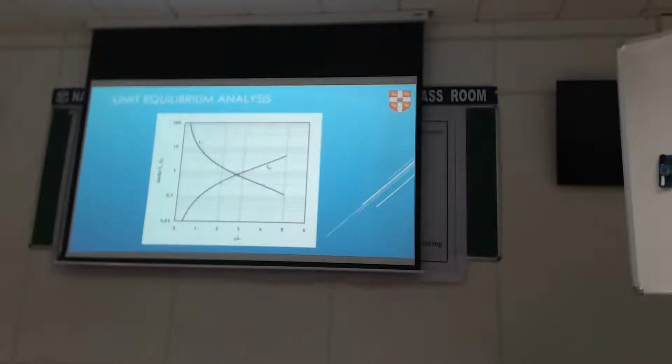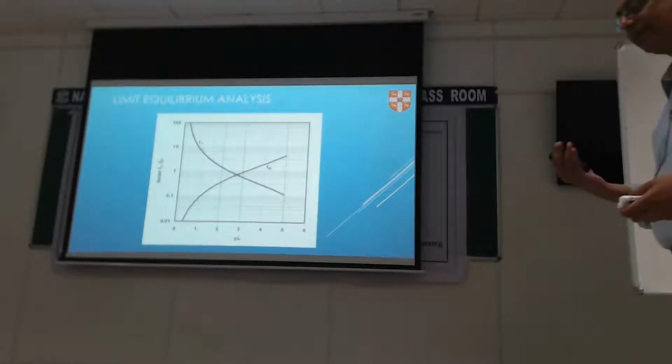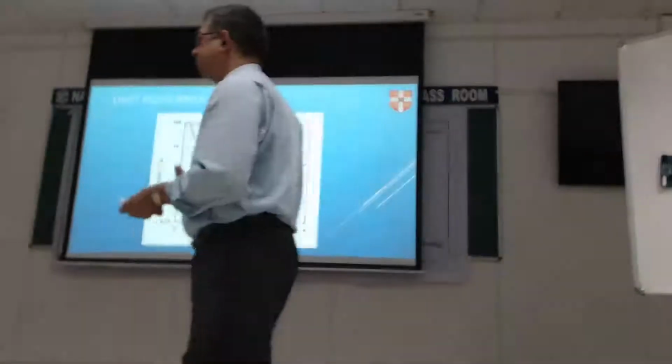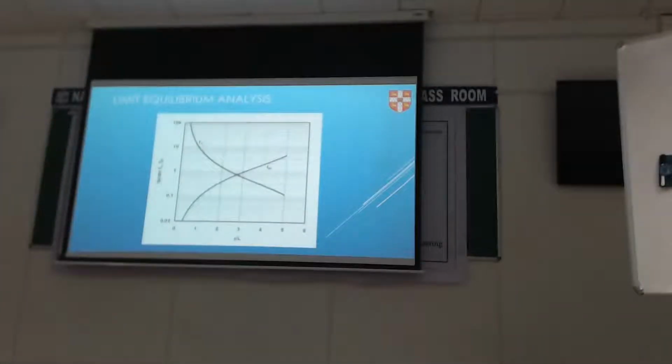Right. So that is the simplest limit equilibrium calculation you can do, and people have been doing something similar. For example, Dobry and Abdul have a similar set, but they don't consider the P delta effect. Our thing is that we should consider the axial load of the pile as well. Otherwise, I'll show you some evidence why this is important later on.